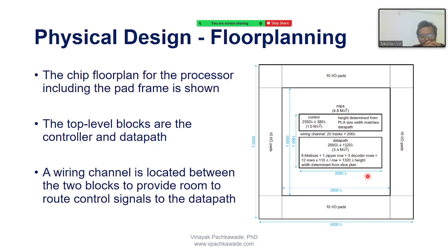Suppose we are considering a 3-input OR gate, and that was a homework actually. We draw the layout diagram of that three-input OR gate, and from that we are finding the whole chip area from that unit cell. That was the homework actually. The homework was just to draw the layout of the unit cells, NAND, NOR, OR and inverters, and using the lambda rule estimate the size of the layout. Wasn't it? Estimate approximate chip area. Correct.